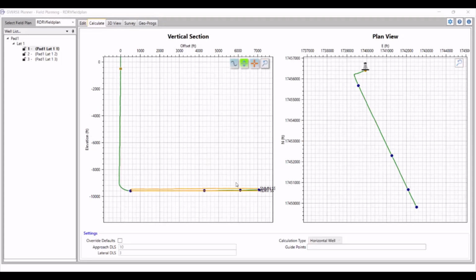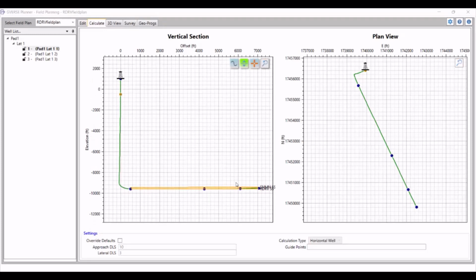So we're going to go ahead and zoom out. One more thing that we can do over here is if you wish to add more target points, you can click on this digitize button, the plus symbol on the top right, and add your target point where you see fit. Once you've added the point, you can move it around, and if you do not like it, you can simply right click on the point and select delete.